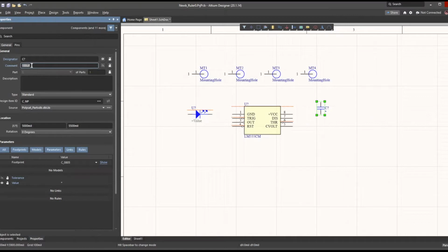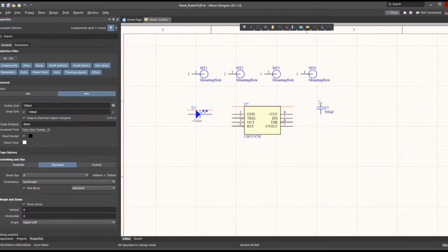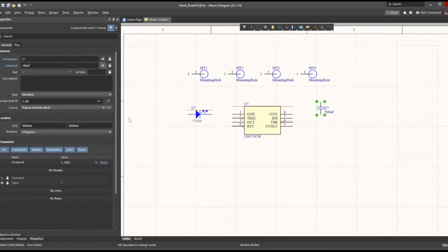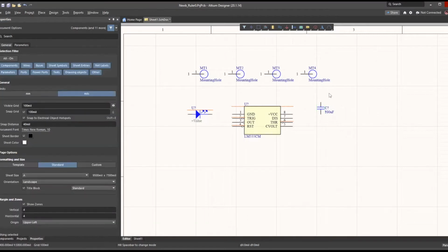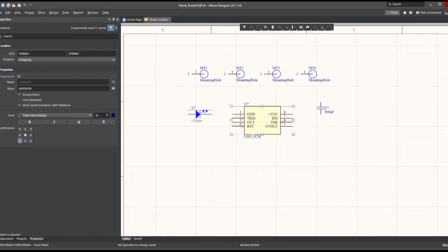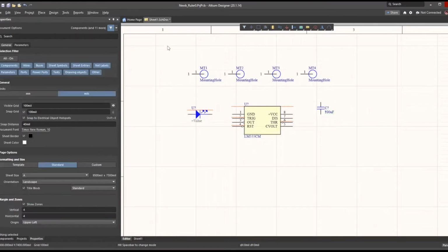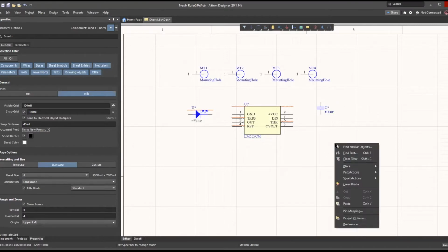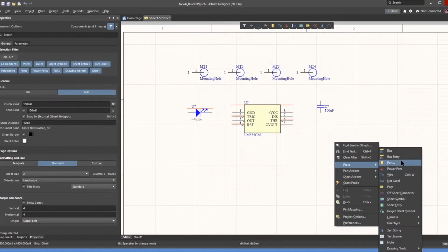And see that it's not showing here, so we're going to check the eye, and now it's visible, and our part's labeled. That's very important. You want the part to be labeled, of course, and you want its units. So definitely make sure if the part does not already have some sort of label, like this LM555, that's a good label, and this didn't have that. If it's not labeled, you'd want to make sure to do that manually. Okay, place another part.